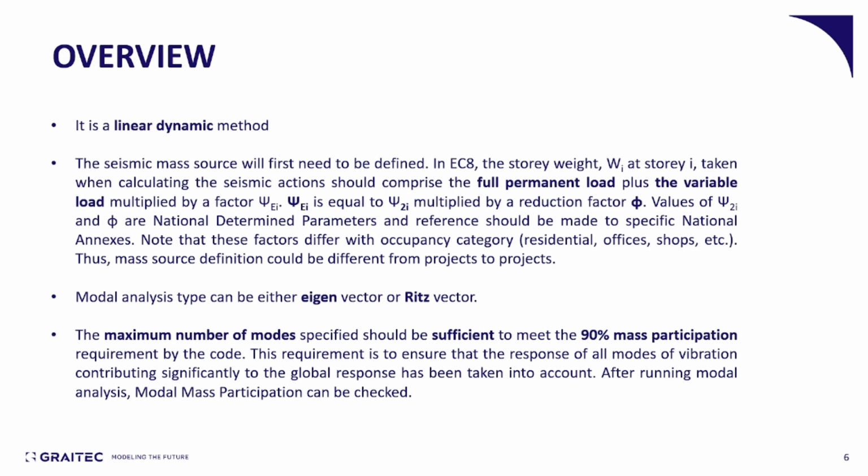This is the requirement from the code. This requirement is to ensure that the response of all modes of vibration contributing significantly to the global response has been taken into consideration. So basically, we need to check after running a modal analysis if there is the 90% mass participation. Otherwise, we need to ask for more modes to be calculated.